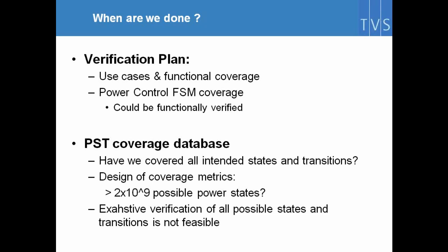So we developed the verification plan to describe the important transitions, the important power states we wanted to reach, and in which modes we wanted to run functional tests. Then from this verification plan, we had coverage metrics and a number of tests.